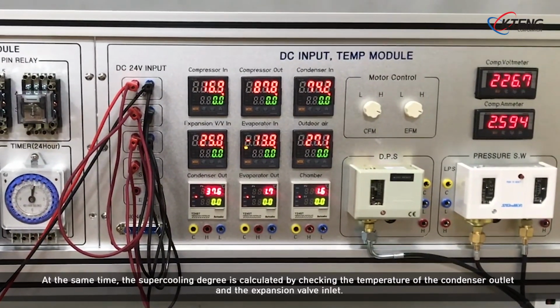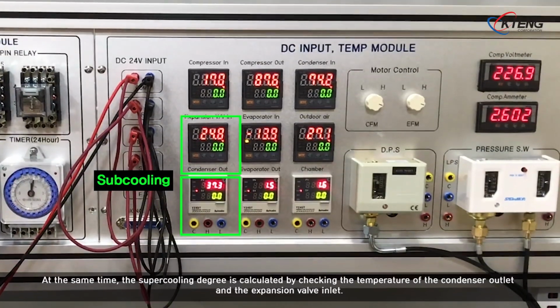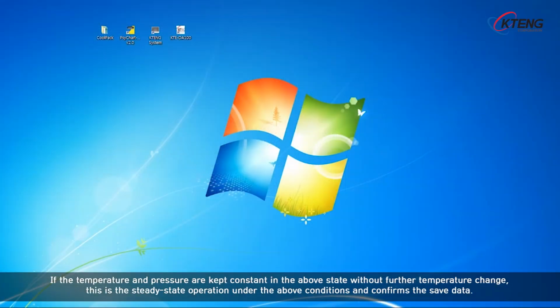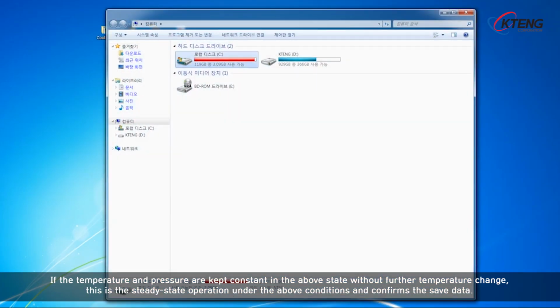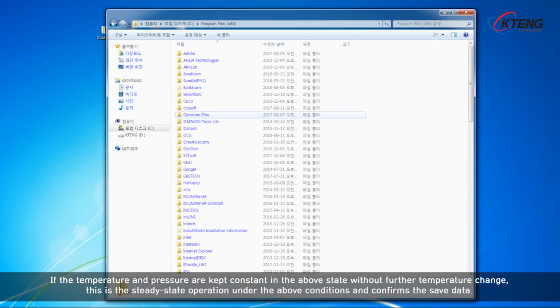At the same time, the supercooling degree is calculated by checking the temperature of the condenser outlet and the expansion valve inlet. If the temperature and pressure are kept constant in the above state without further temperature change, this is the steady-state operation under the above conditions, and confirm the saved data.